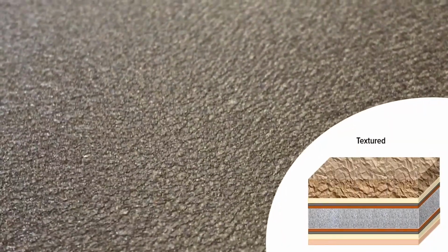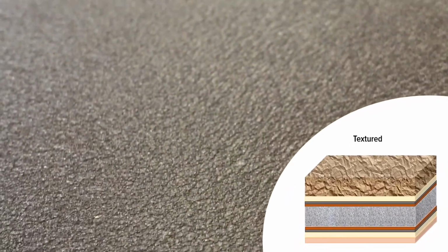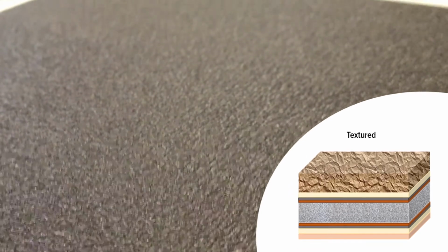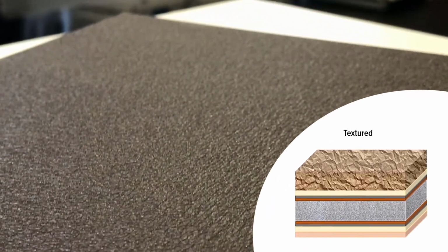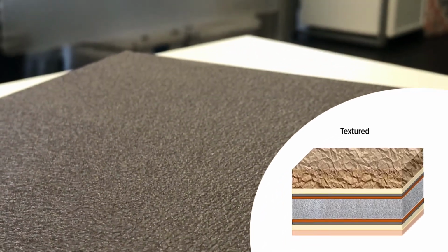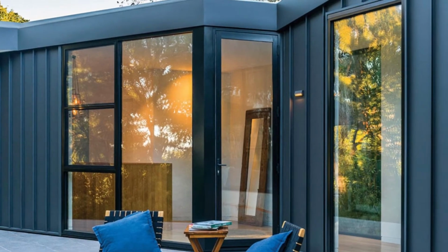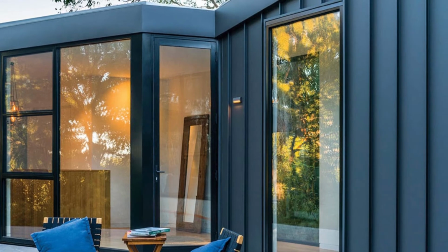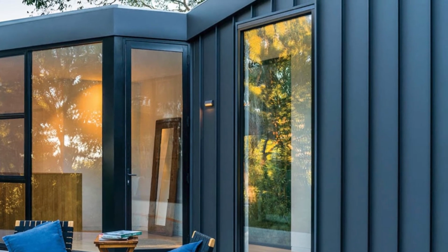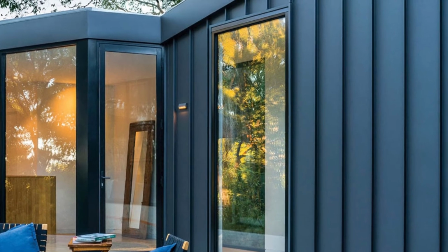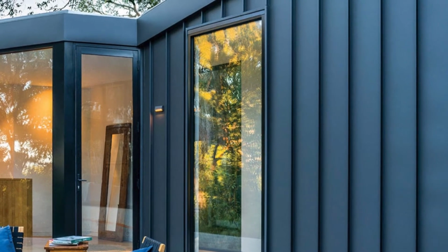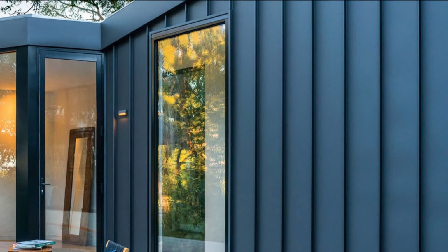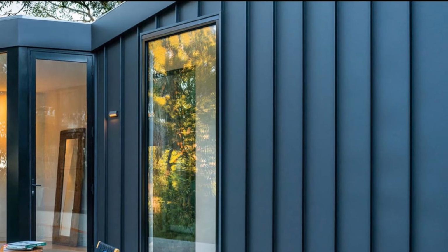The paint top coat can be formulated to have a visible, tactile texture. This can be achieved through the chemical properties of the paint that result in crinkling of the surface during the curing process. This crinkling is specially developed so that it does not impact the paint's performance or warrantability. Alternatively, texture can be achieved through adding particulates to the paint itself, which creates surface variability. The rougher texture impacts multiple senses to add to the depth and the viewer's perception of the surface. This texture can also reduce the glare, or light reflection, on the surface.